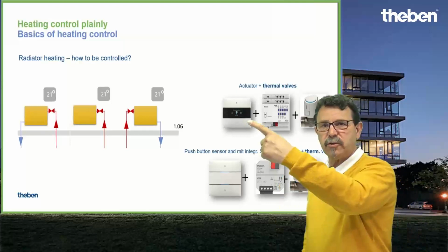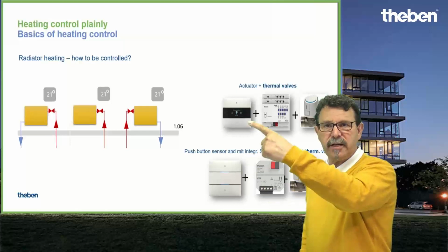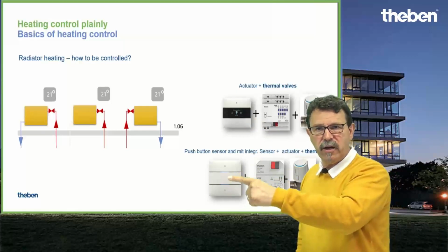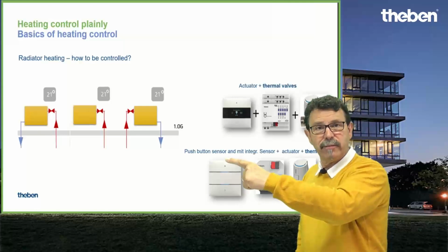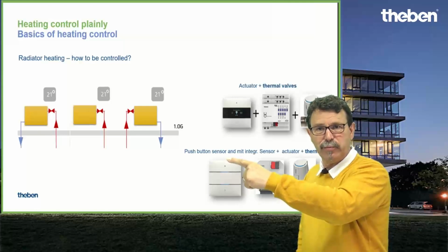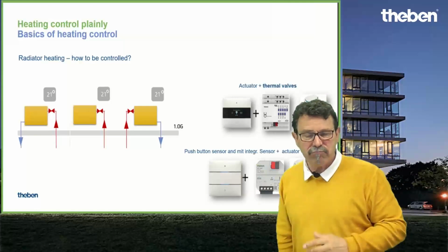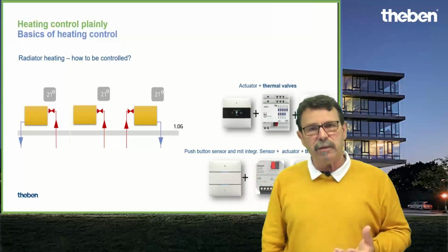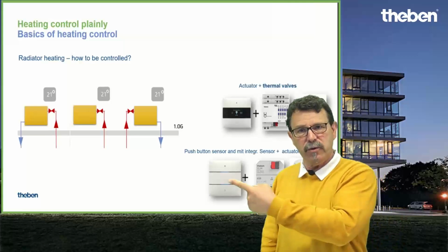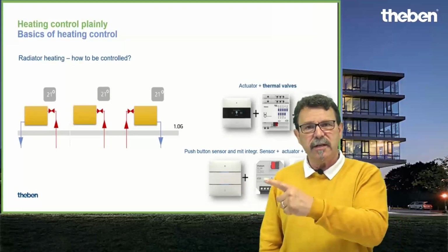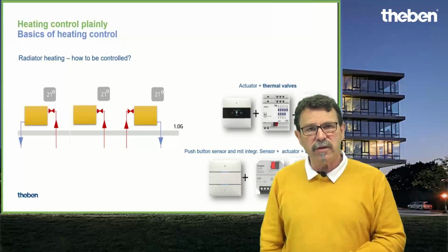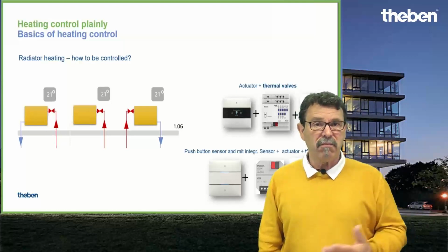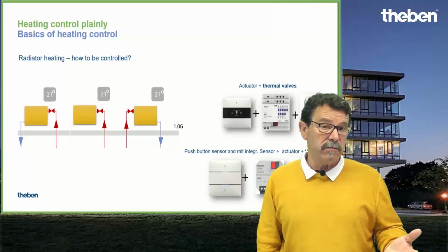And the room temperature controller, for instance, either with the external remote, so you can adjust your set point, or here you have the temperature probe, which is inside this push button. With this room temperature, which is measured here with the Eon 102 in this case, you address the heating actuator, which is to be set as a controller, and then the heating system is running on its own.